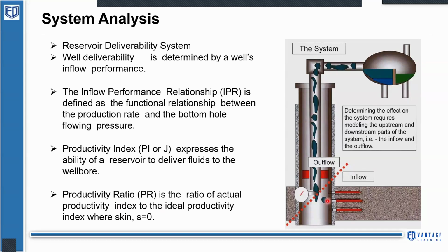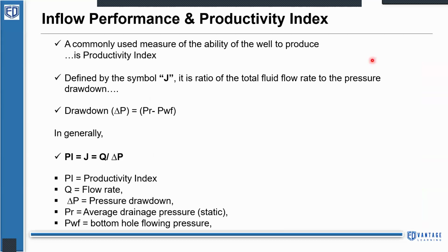If we talk about the bottom hole node, and the joining point between out wellhead to the in tubing will be the surface node or the wellhead node, and there is something else between the choke and the wellhead, which is a choke node. So we define three general nodes. One is bottom hole node, wellhead node, and the choke node in nodal analysis.